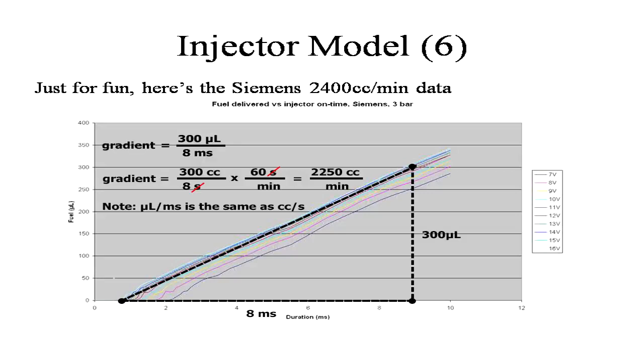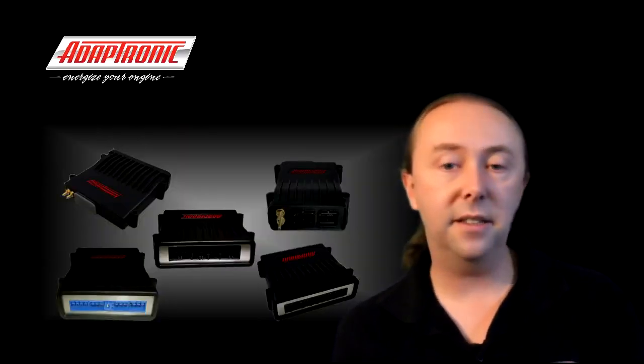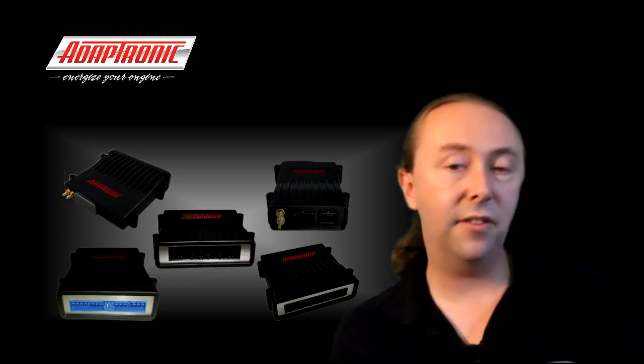Now in practice we've actually got several lines here, and this is because each line corresponds to a different supply voltage. So we've measured it every volt from 7 volts up to 16 volts. And you can see that the higher voltages make the injector open earlier, and also it should be fairly obvious that once the injector's open, the flow rate is pretty much the same, that is, all the lines are parallel. Now if you have sharp eyes, you should also be able to see that below about 25 microliters of fuel being delivered, the curve has a bit of a kink to it. Now this is because of pintle bounce. You only see this on underdamped injectors, so overdamped injectors like the ID2000s and so on don't exhibit this kink in the curve at all.